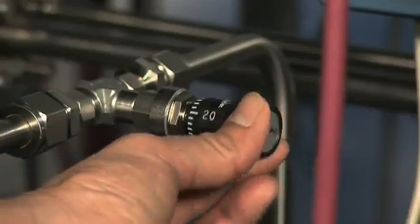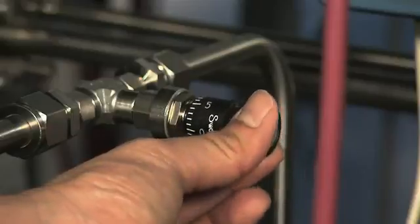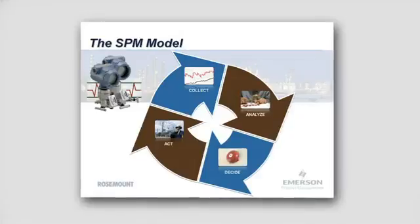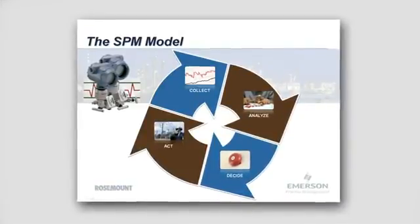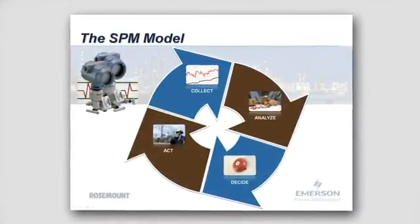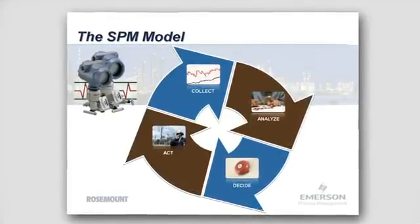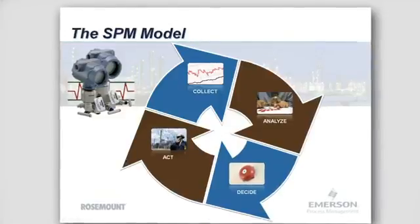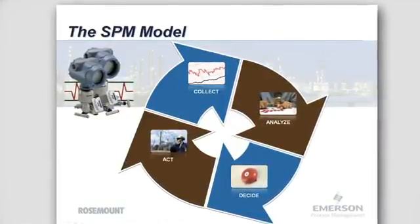For example, if an impulse line were to become plugged, the operator would not see a change in the pressure measurement. However, if we utilize the process variability seen by the 3051S and follow the 4 simple steps of the SPM model to collect, analyze, decide, and act, we can detect and prevent abnormal situations in the process.